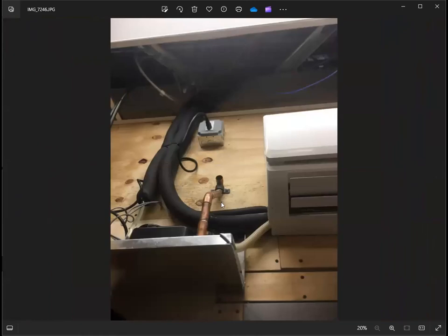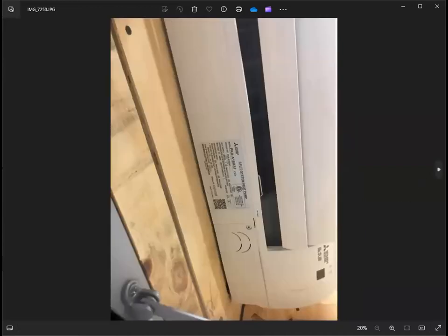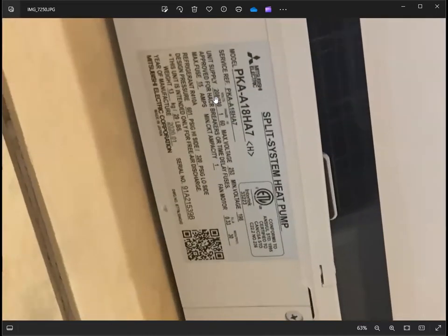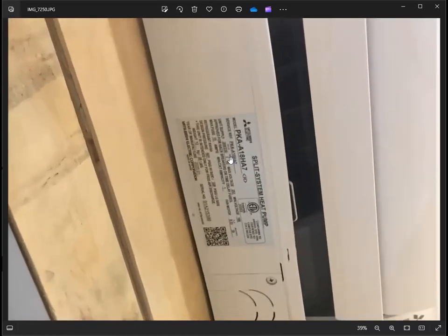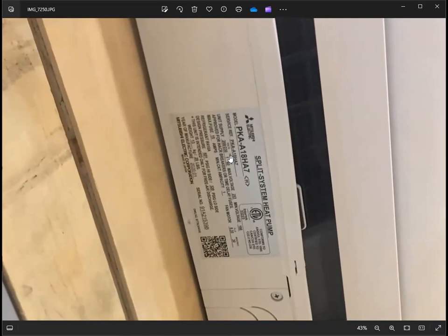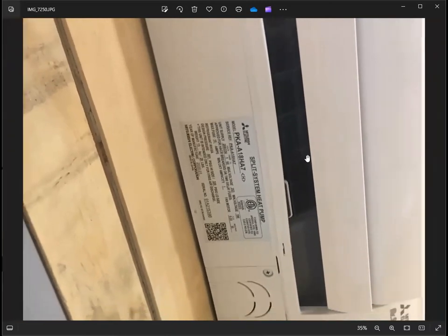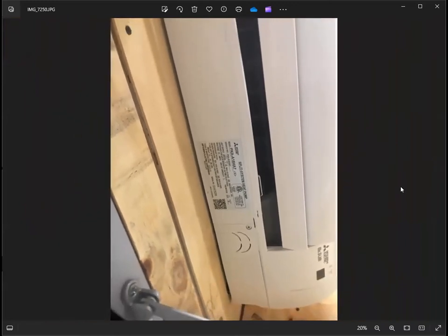This is the installation of your refrigerant piping, computer area. So this is the split type unit. How they installed it should be based on the manufacturer's installation recommendation. And you need to identify the manufacturer and model number. So it needs to comply with the drawing specs and the design. Either way, as I said, if it doesn't match the drawing, you need to ask for approval from the engineer or approved submittals that this is acceptable for the job.